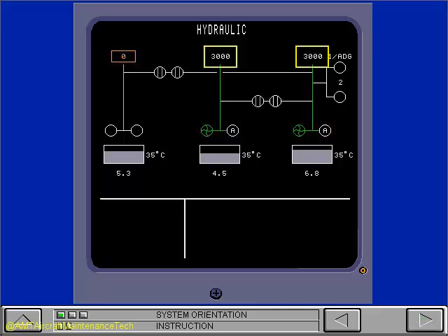Hydraulic system pressure shows in white digits at the head of each system in increments of 20 psi. The white digits become amber and show in an amber box when the pressure is less than 2400 psi or more than 3500 psi.